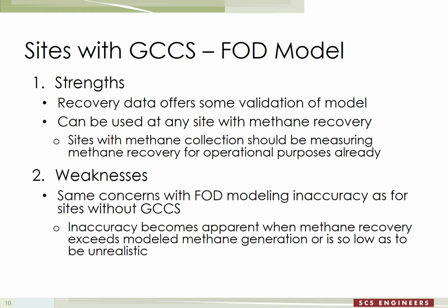The strength of using the first order decay model on a site with a gas system is that at least you have some data to validate the model, and then you can use that for calibration. And most sites that have gas systems really should have the kind of data we need in terms of the flow and methane content of the gas that's being collected over time. Obviously, it has the same weaknesses involved with the model and the inaccuracies and uncertainty.